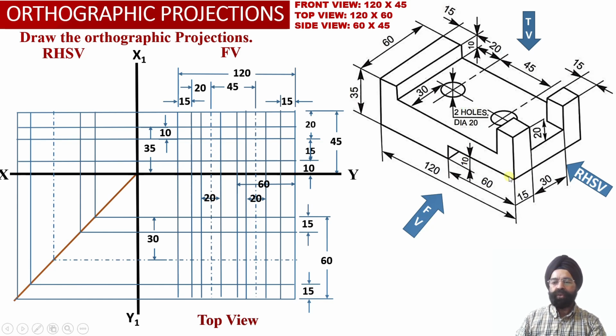We can check. So this position and this position describe the rectangular slot which will be visible to the observer. So now we can check as we move along from the right hand face, 10 millimeter above the base of the solid. Now this is the rectangular slot which has been cut on the right hand side portion of this horizontal web.